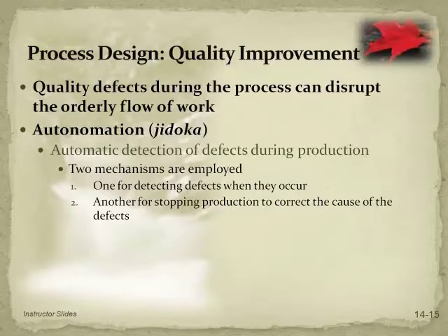Well, instead we came up with a process where we had a microprocessor, basically a computer, that was able to detect each individual wire as the assembly operator was making that connection to see if the connection point was correct. And if the connection point was correct, then a green light emitting diode would turn on, indicating to the operator that that was correct.